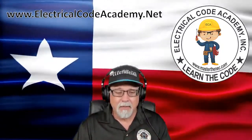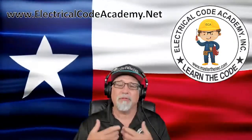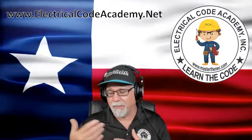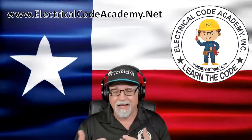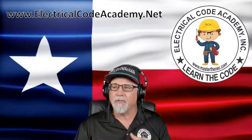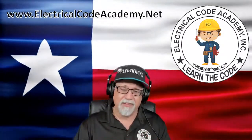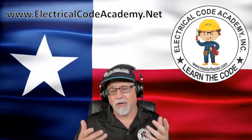That's great. We just have to be careful when we're explaining things that are important, like grounding of a system. And we have to understand it. For example, if he has metal water piping in the building, you got to bond it. So we already saw that in the code. If you have a water pipe ground, you have to supplement it. It's not a this or that for this case. So things that he needed to learn a little bit, but hopefully you learned something as well.